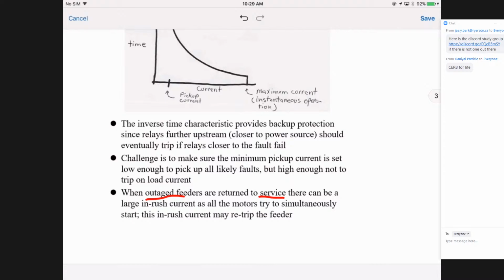When you clear the fault and close the breaker, it may have a high inrush current to the motor. If it is just one or two motors which we turn on and off, then it's easy to deal with in the feeder.